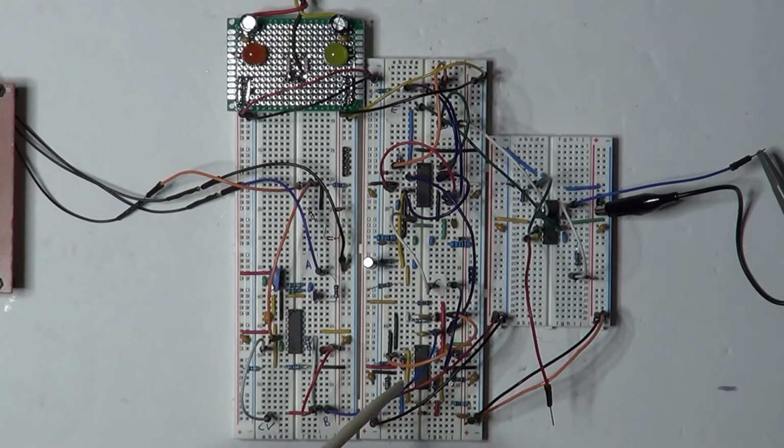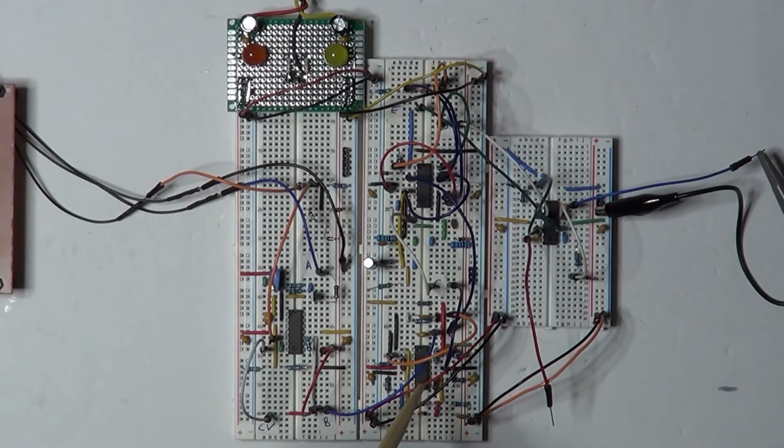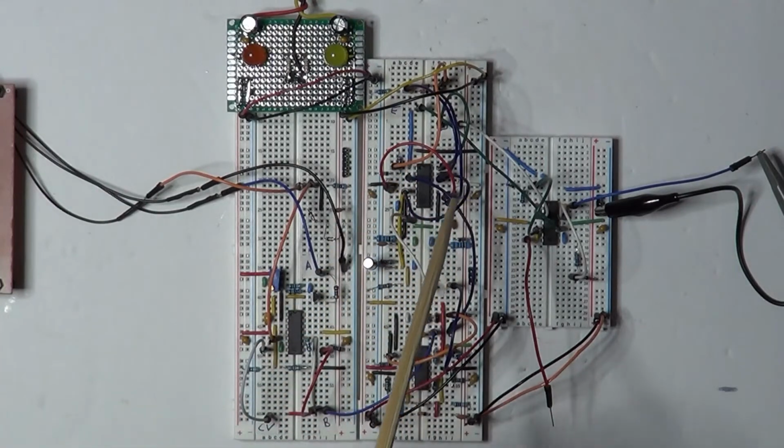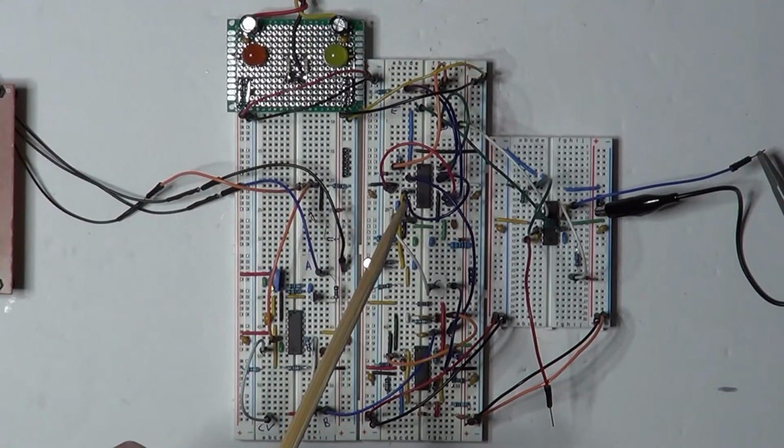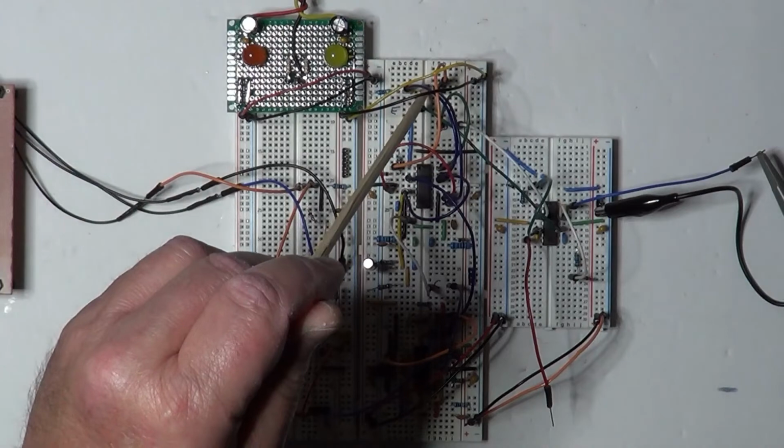Inside here there are also the other 2 op-amps that are used to adapt the impedance and act as a buffer for the signal coming out of the 2 diodes. And then there is one op-amp that is used as a voltage comparator to remove the noise in between 2 different triggers. This other section over here is the one that removes the trigger generated by the key release and eliminates it. And you can see here the 2 diodes.